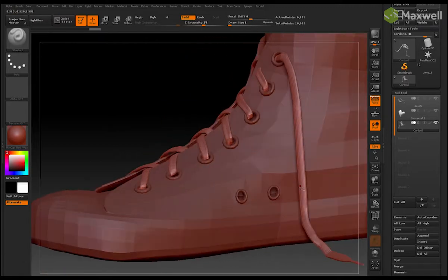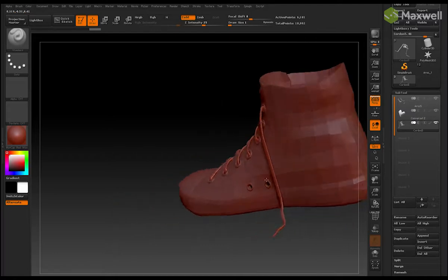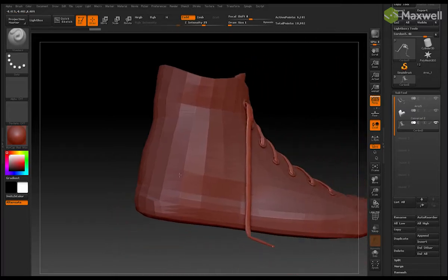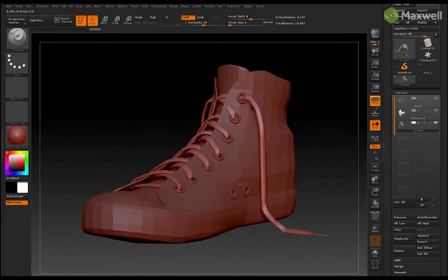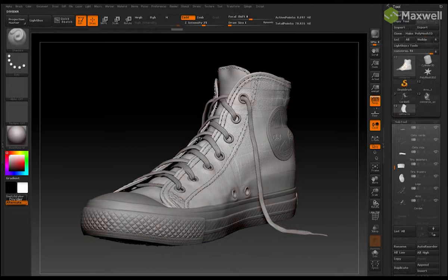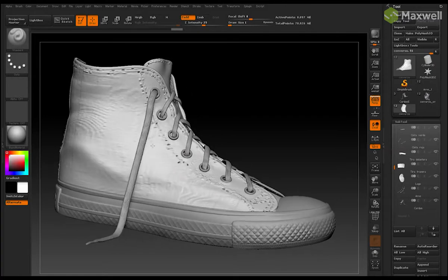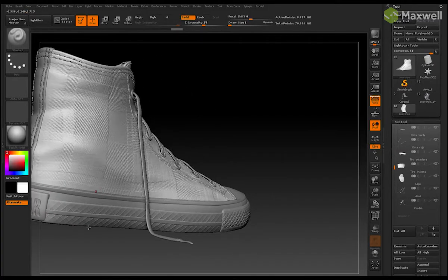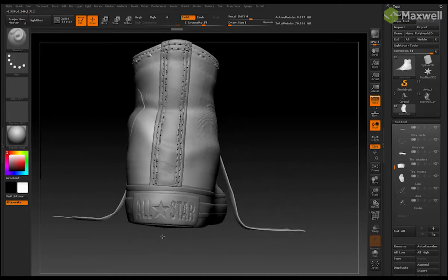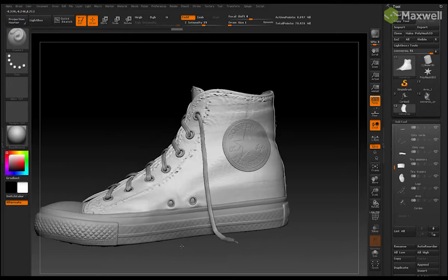It's easy and fun. You can make details like wrinkles and creases on your model, adding subdivision levels to the object. But don't worry if you add millions of polygons, because you are only going to need the low poly object for rendering. With the high poly model, you can get texture maps, normal maps, and displacement maps with total precision to render them later on the low poly object with Maxwell Render 4.